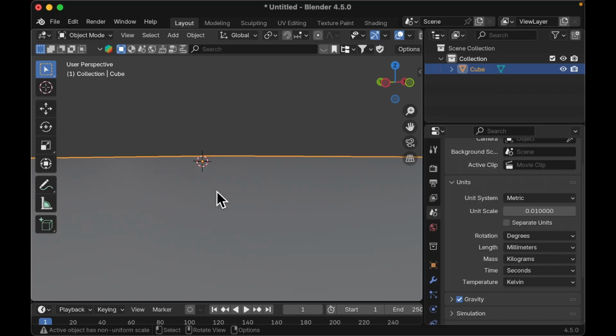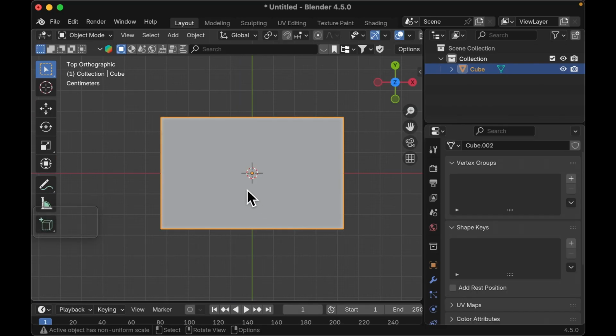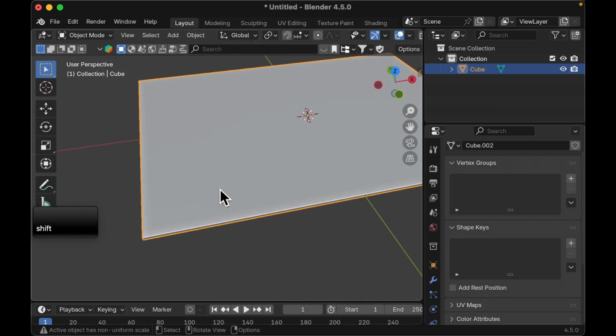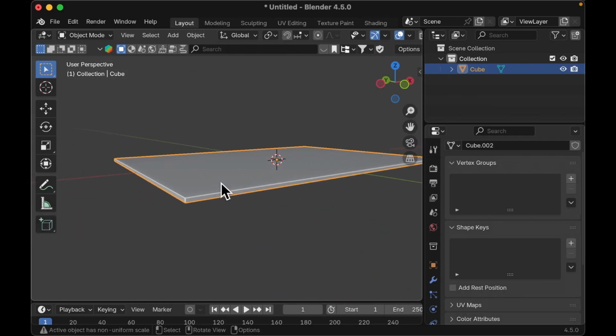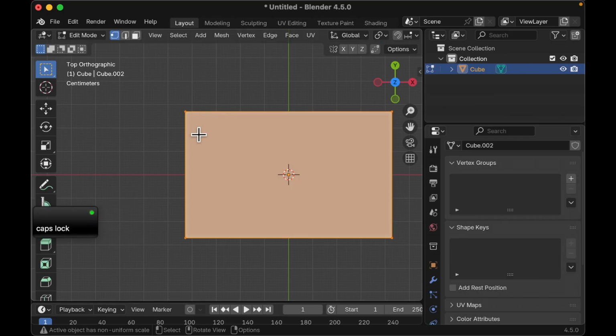If you get any clipping, you can come to this N panel and change the clip amount here. Now we have our shape here. We have our card shape. The next thing we would like to do is create those curved edges, those rounded corners that cards usually have. I don't just want to go into edit mode and create those rounded corners with bevel manually. That's going to be destructive. It means I can't change it later.